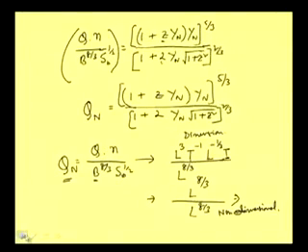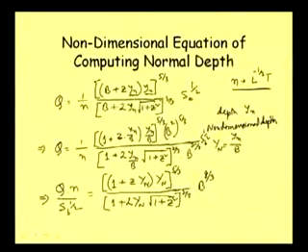Say we can talk about this relation. In this relation we have got one Yn, then this Yn we should put here and check whether the discharge we are getting by using this approximate value of Yn is really satisfying our required discharge or not. If the difference is very small, we can take that approximate solution as the correct one.